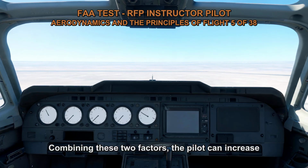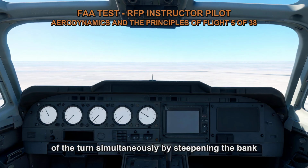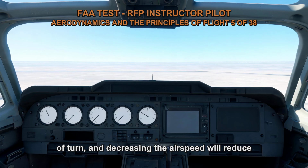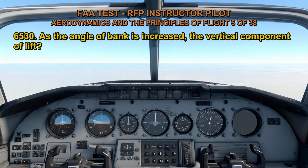Combining these two factors, the pilot can increase the rate of turn and decrease the radius of the turn simultaneously by steepening the bank angle and decreasing the airspeed. Steepening the bank angle will increase the rate of turn, and decreasing the airspeed will reduce the turn radius.